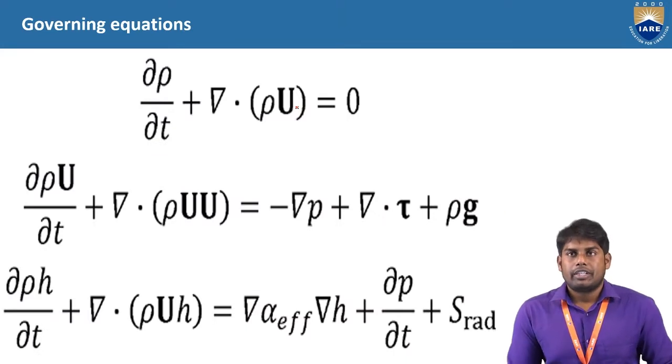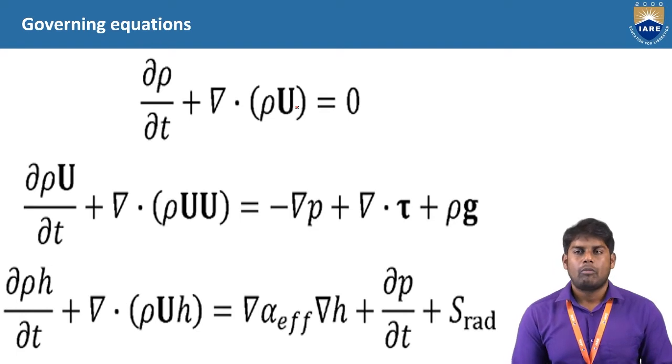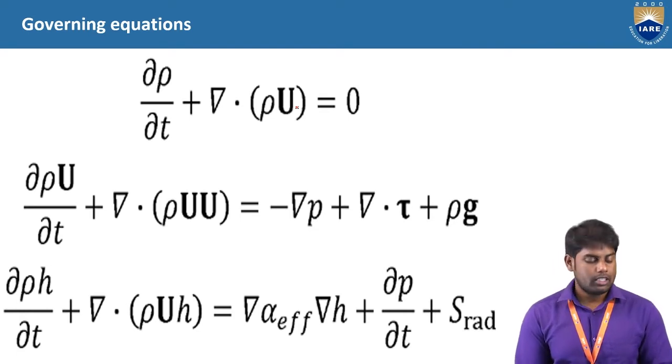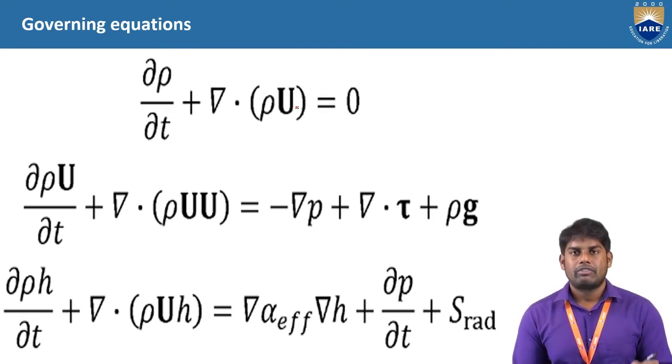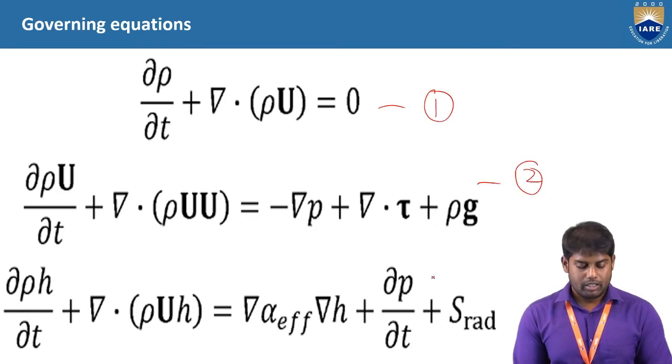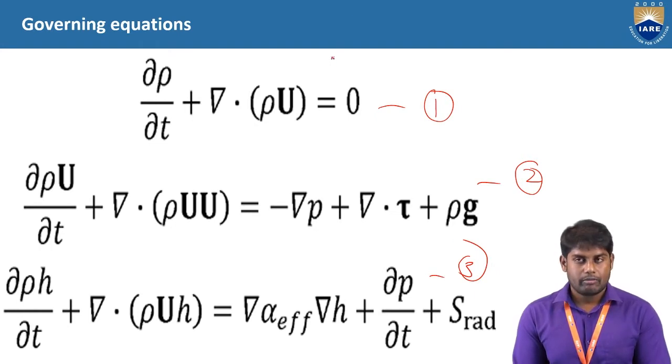Yeah. So basically, the governing equations are very important. Any fluid flow problem or heat transfer problem, if you consider, the governing equations will decide the flow phenomena. So this is the continuity equation, this is the momentum equation, and this one is the energy equation. When a fluid particle is moving from point one to point two, these equations will govern the fluid motion.